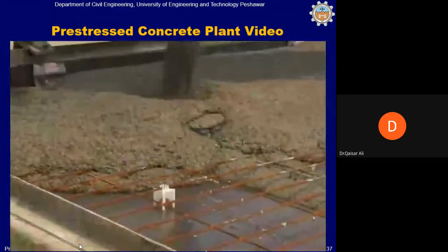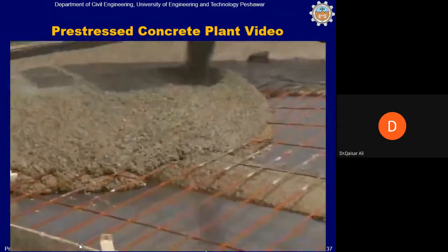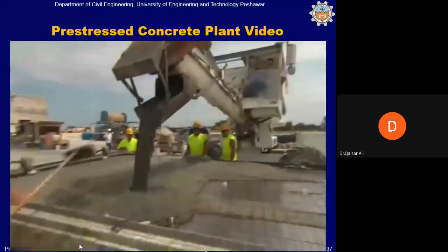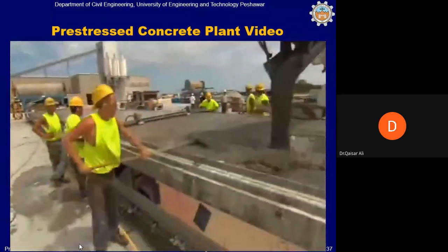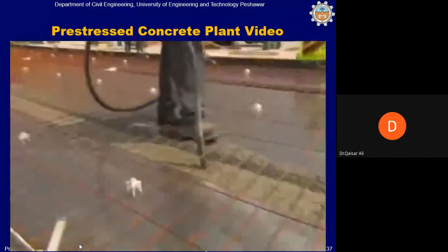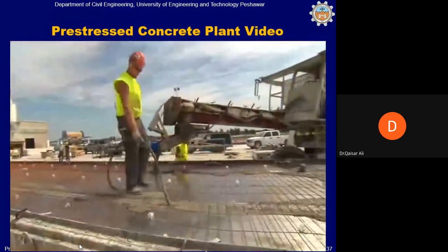A self-consolidating concrete is being used to cast these particular double T's. With this type of concrete, vibration is not required to consolidate the concrete. However, minor controlled vibration is used in the double T stems to help remove air from the sides of the form, reducing bug holes in the stems.